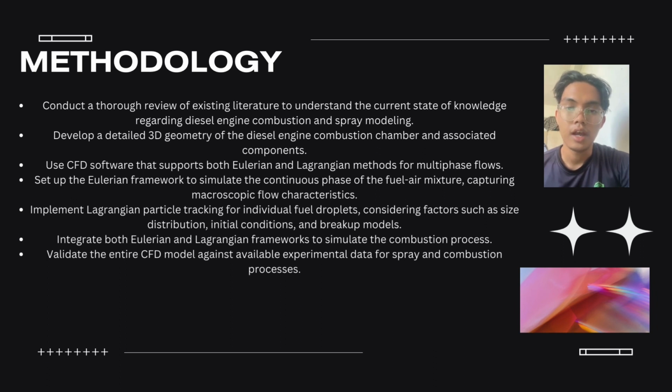Okay, next we want to set up the Eulerian framework to simulate the continuous phase of the fuel droplets for the fuel injection, capturing macroscopic flow characteristics. Then we want to implement Lagrangian particle tracking for individual fuel droplets, considering factors such as size distribution, initial conditions, and breakup models. Then we want to integrate both Eulerian and Lagrangian frameworks to simulate the combustion process, so that we can analyze both methods and know which one is the best for the data about this case study. Then we will validate the entire CFD model against available data for spray and combustion processes.